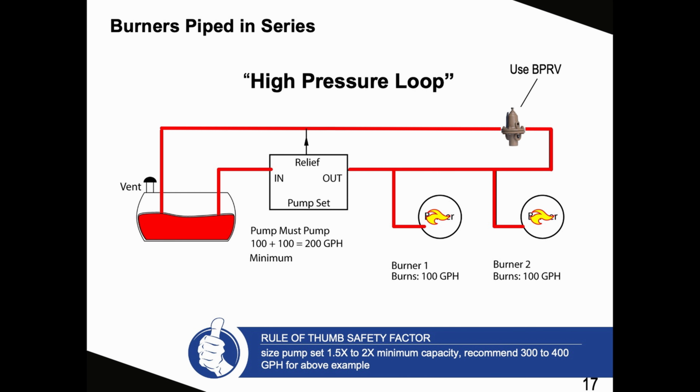But again, this is a high pressure loop typical of industrial sized applications. Right, so interesting scenario. The duplex pump skid, in essence, is really creating the pressure at the nozzle on the burner for firing. And the back pressure regulating valve is what you set the pressure at. It's not the burner side pump that's creating the necessary pressure for atomization. It is the loop itself.